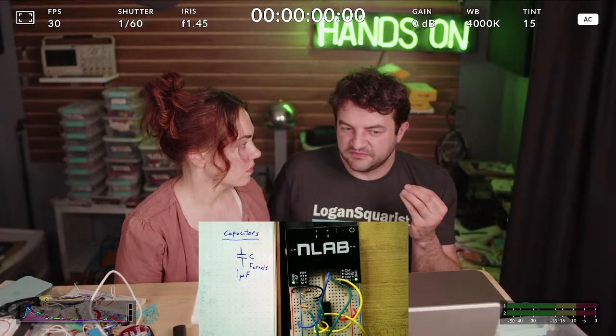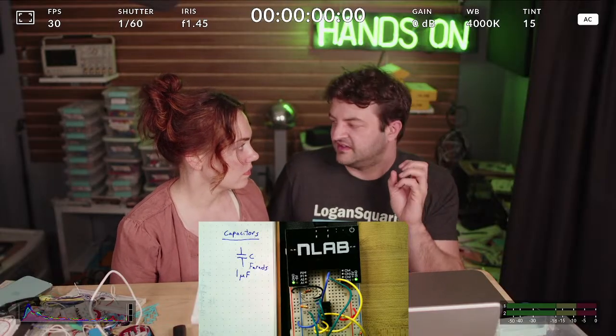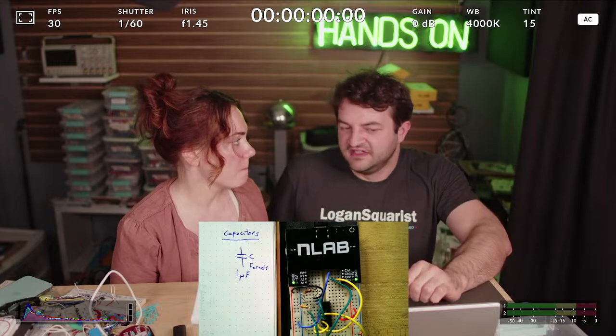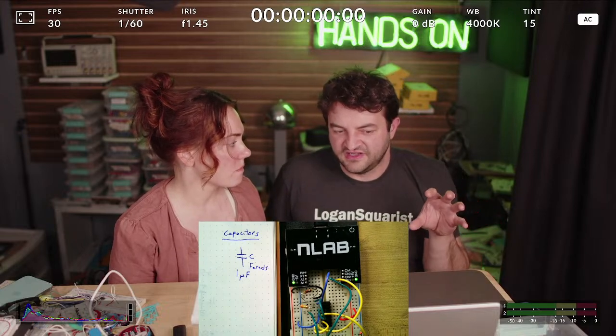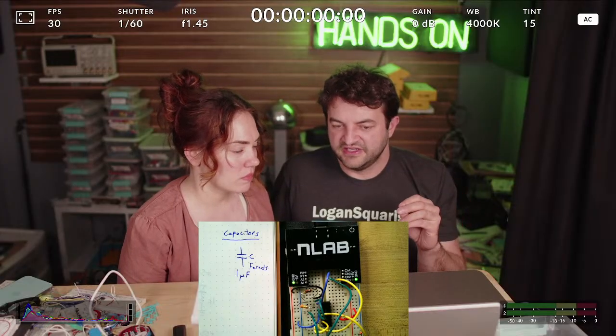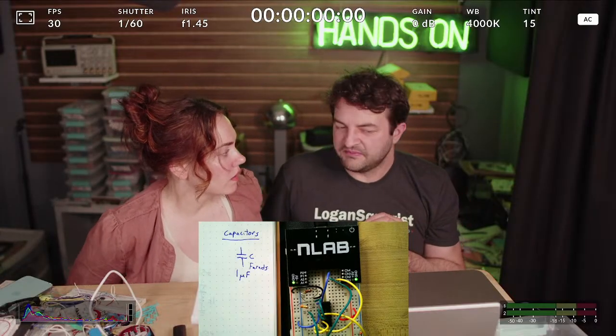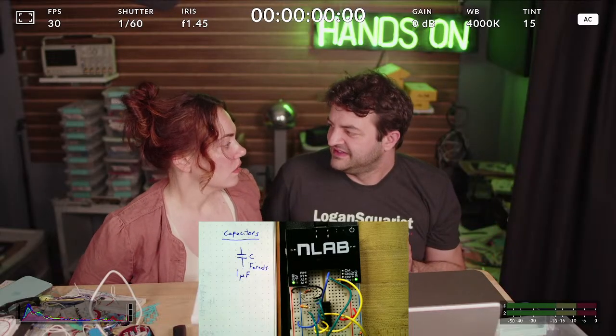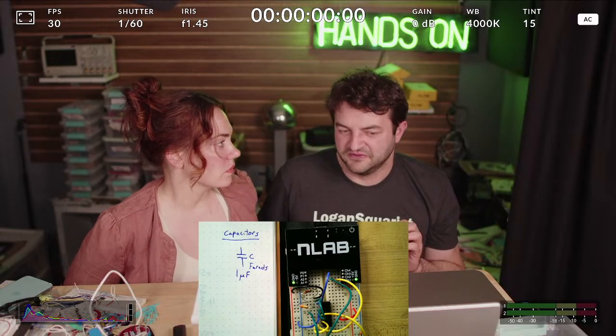So the flash would only be on for like a split second, which is what you want for the flash anyway. Yeah. So what you're doing is you're slowly stealing energy from the battery and then delivering it in an instant. Yeah. Because it's the same amount of power over time. It's just that the LED only needs to be on for like a millisecond.